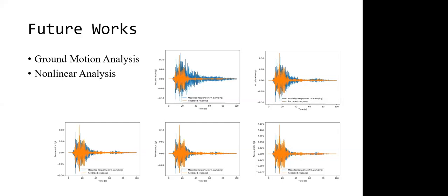For example, one of the most interesting things, which I didn't mention last time, turned out to be a critical factor which not many of us know. There is a limit on the number of digits you can use in OpenSees numbering. 2 to the power 32 minus 1 is the biggest number you can use, which turns out to be a 9 or 10 digit number. That was restricting me from using 4 digits for each grid, first 4 digits for x, next 4 digits for y, next 4 digits for z, because it was becoming 12 digits, so I had to stick to 3 digits each. So I was using 4 or 5.